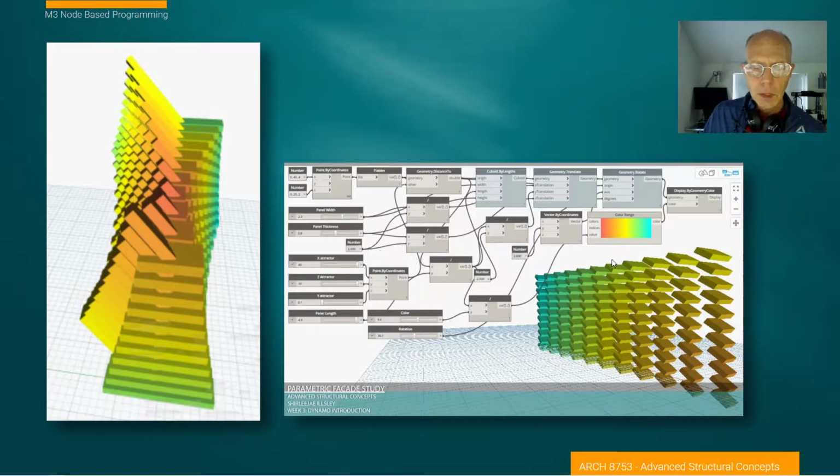And our original introduction, just a step as we're going through this in computer viz, was to, and some of you may have had this and some of you may not, but I'm introducing it now again just to help familiarize us with it. In computer viz, one of the last projects we do is to look at computational design. So in this case, we're taking panels. We're creating a panel width, a panel thickness, as you can see here. And we have an attractor, a point out in space. And we make a relationship between these panels that we build in an array that we set up.